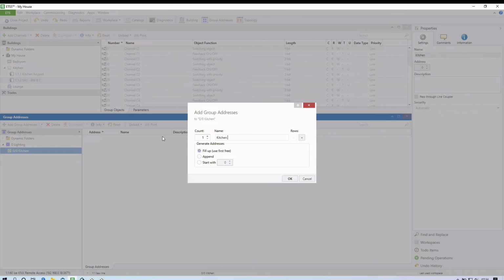the group monitor, which enables you to see the traffic on the bus, you don't have the benefit of all these different filing labels. So all you will see is the group address name. So it's really important the actual group address name has useful information in it. So we're going to say it's the kitchen. We're going to say it's the circuit we're controlling, which we'll call downlight.